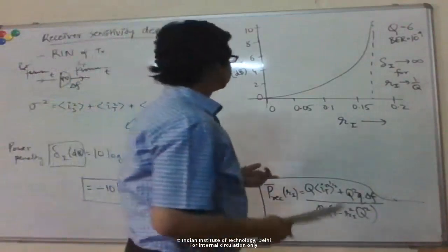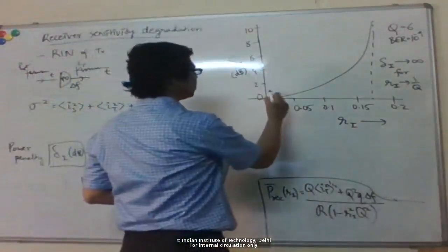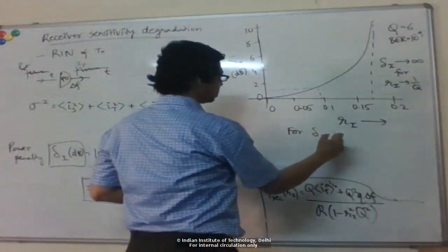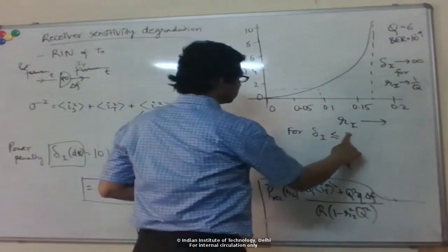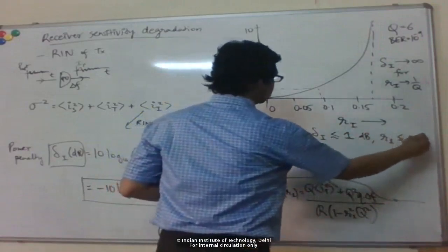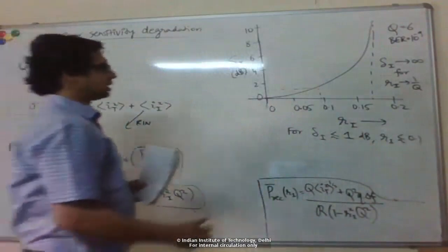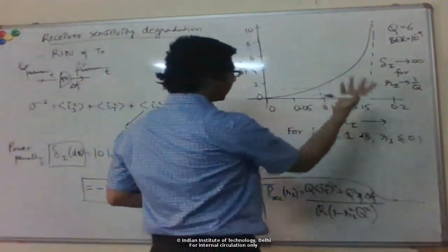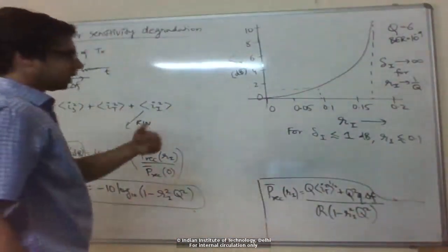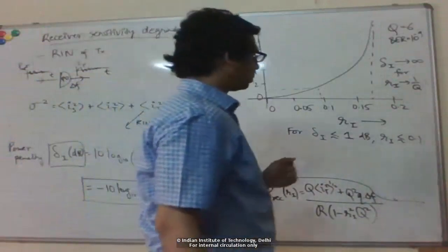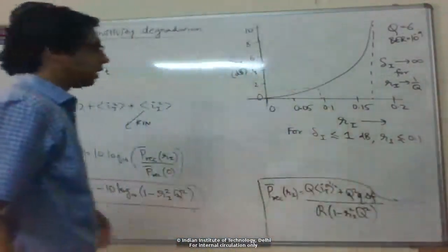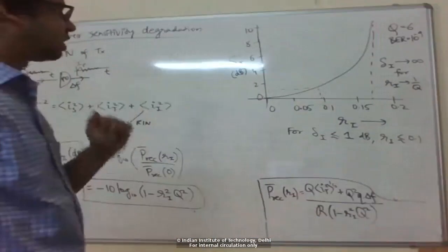Okay, so you can see that typically, if you want your power penalty to be less than 1 dB, that means you want this Ri to be less than 0.1, or a received optical SNR of greater than 10 dB. We just discussed that state-of-the-art semiconductor lasers typically have Ri of 0.01. So that's much smaller than this. So you might wonder, why are we even considering this?